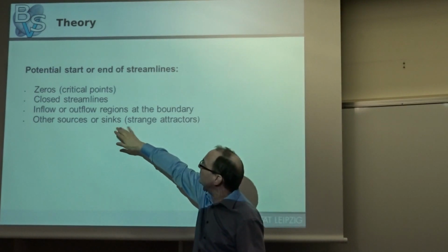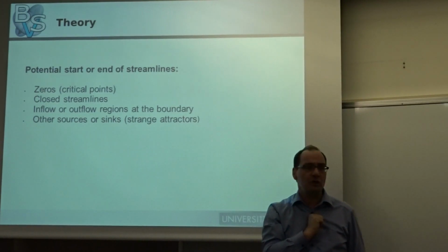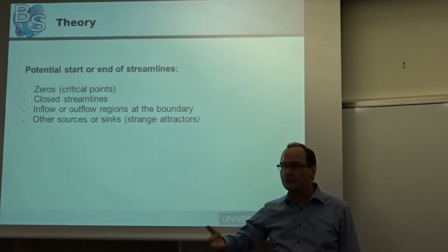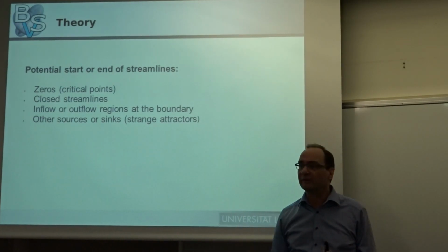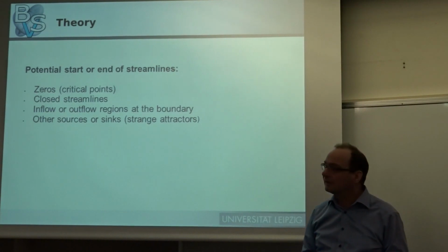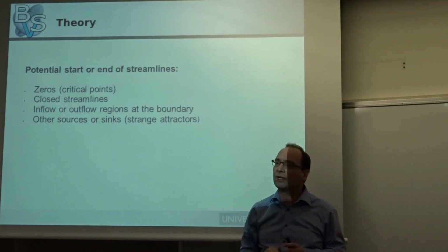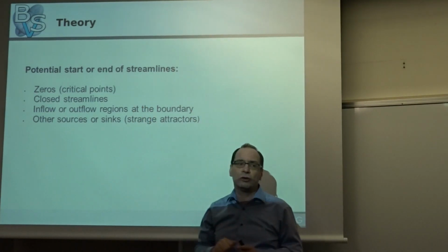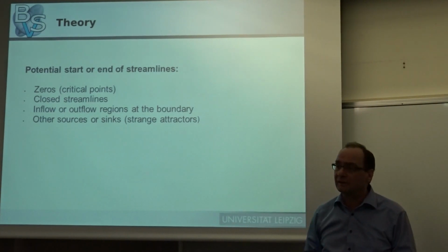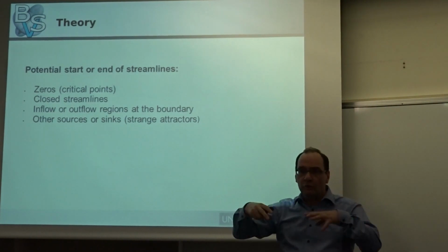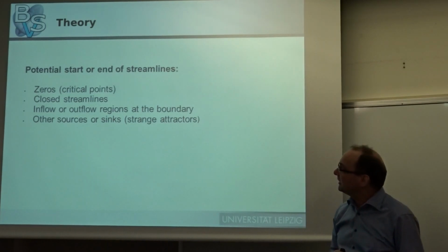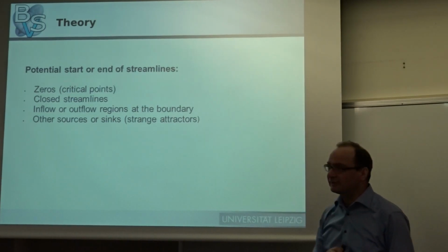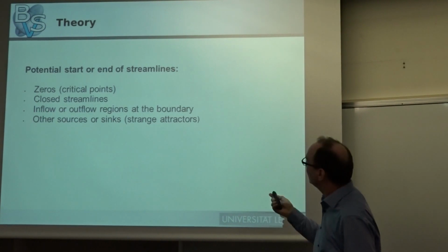And if you go to 3 dimensions, then there are things like strange attractors, typically named the Lorenz attractor or the Smale horseshoe. If you have ever heard about these, they are typical examples. And there are algorithms to exactly or approximately find these structures so we can, for steady flows, structure the field. Why is this interesting in applications?